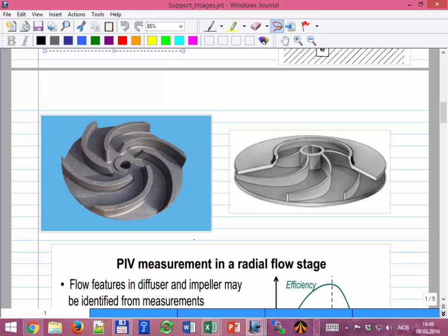Okay? And then, as it's rotating, the fluid comes out of here, then comes back inside. It's just going out, back in, and then it's entering into the next impeller. Usually a pump is not made of only one impeller because one cannot increase the pressure very much. It's only a little bit, but you have an arrangement of maybe 60 or 80 of these in a pump. Okay, so I'm going to pass this down so you can see how it looks.